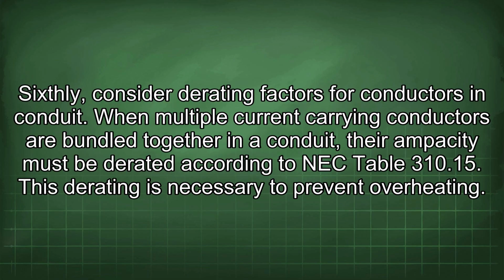Sixthly, consider derating factors for conductors and conduit. When multiple current-carrying conductors are bundled together in a conduit, their ampacity must be derated according to NEC Table 310.15. This derating is necessary to prevent overheating.